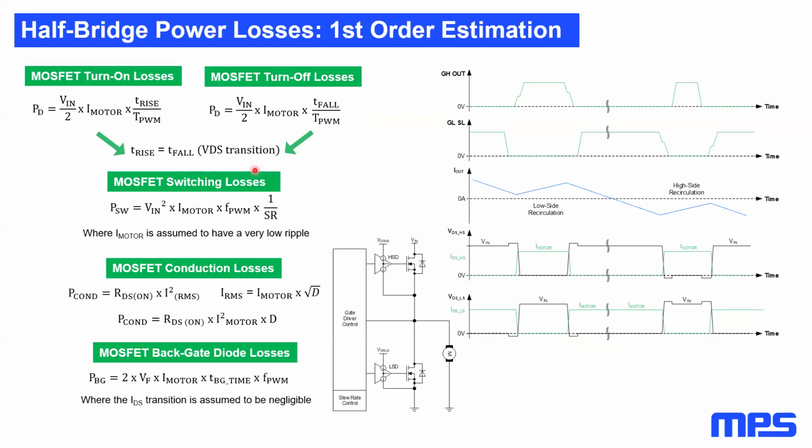Christoph, when Christoph explained how the waveforms in a half bridge work, with current going out of the switching node, he said the current has to keep flowing when we turn off the high side, and it will flow in the body diode.